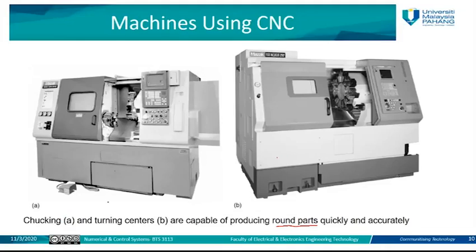As we said, some of these centers perform multiple tasks, not only lathe, not only milling, not only drilling. They can combine 2, 3, 4, up to 5 tasks on the same machine. We just need to modify the program inside the MCU and adjust some of the tooling, like the heads and so on.